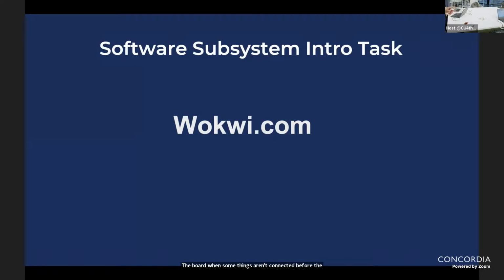It gets a little tedious, but I'll try to explain it as best I can. This board, we will connect the USB to it, and it will simply be powered up. So there's a VCC pin, and VCC is simply a power pin. What I'll try to do is connect this power pin to the breadboard, so I can power up the entire breadboard. And this is what we call a breadboard for anyone that doesn't know. There's metal under all these pins, and they just make sure the pins are connected to each other.